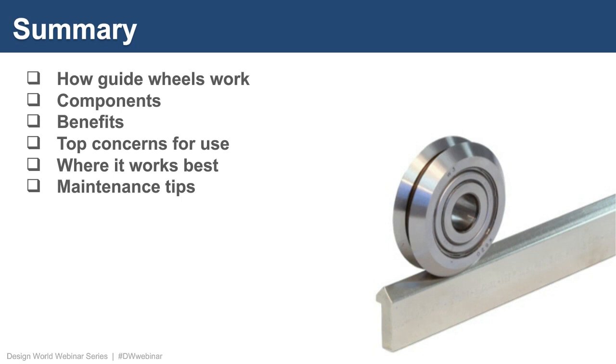We looked at all the different bearing technology protections that there are: seals, shields, seal shield, and the double seal washdown version. Then we talked a lot about the concerns that you might have for use in your application, how to calculate the life estimate. We looked at maintenance, how to keep it running a long period. You know, we're mostly concerned about lubrication. We looked at lubrication kits like the lubricator and the wheel cover.